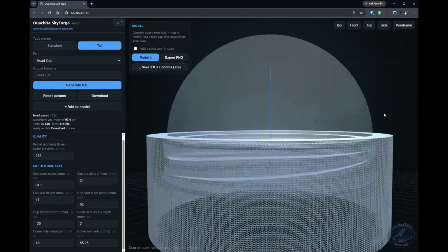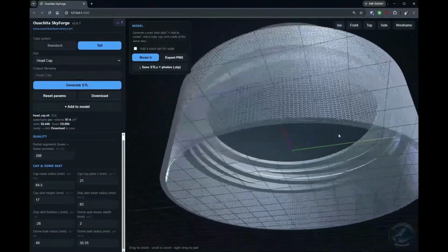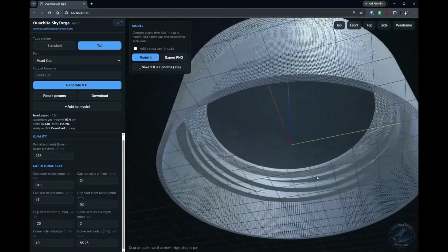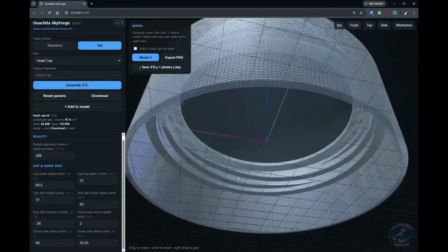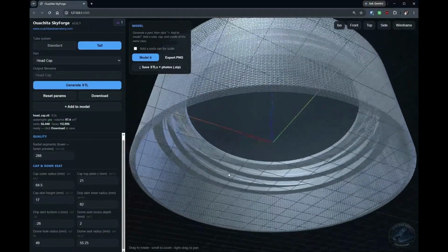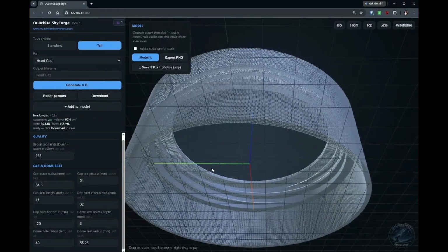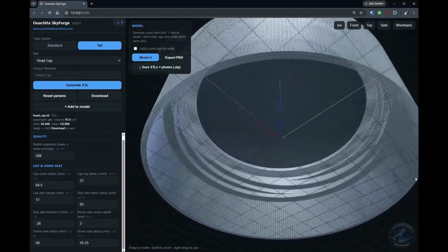So, see the underside, see where the threads are. One thing to notice, you'll see these threads have multiple starting points, so that gives you the option to have a quicker tightening. A 27-degree turn completely tightens this lid down. So you have a thread start there, there's another one there, where some screws have one single start thread. This has 3 different levels where it can start at, so it just allows you to start tightening things faster.